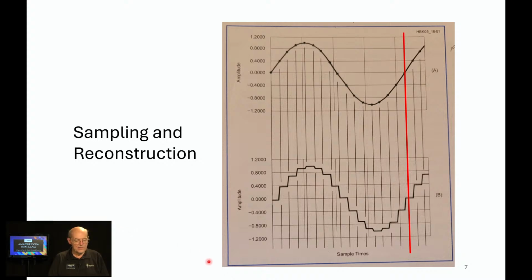So if we use a filter, we can convert it back, but it's not going to be 100% faithful reproduction because of that quantizing noise. We're guessing between the stair steps. Another thing about square waves, or what we're seeing here, very sharp rise times, they're very rich in harmonics, which is another reason why we need to filter it out.